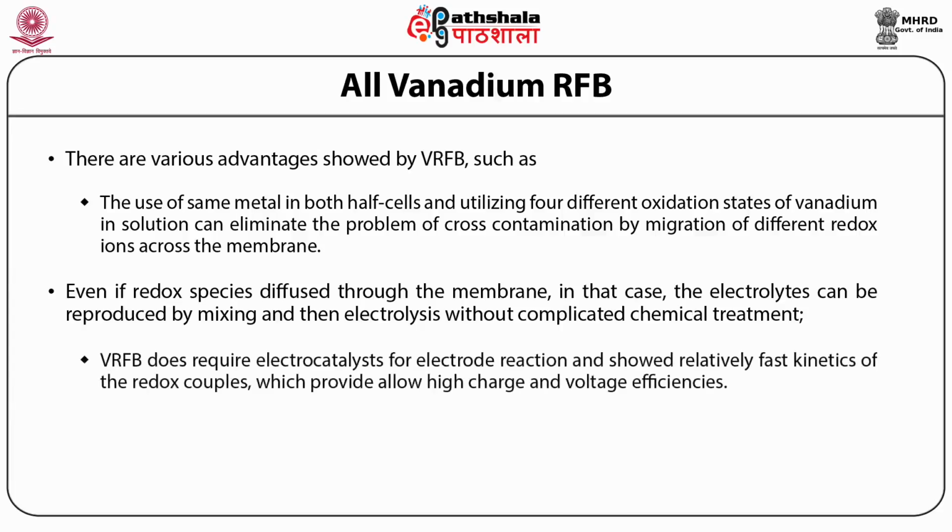Second, the VRFB does not require an electrocatalyst for the electrode reaction and shows relatively fast kinetics of the redox couples, which allow high charge and voltage efficiencies. An overall energy efficiency of about 70 to 90% has been observed with a 1 kilowatt VRFB stack.